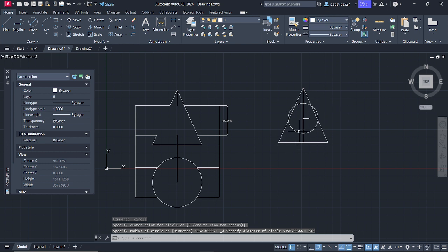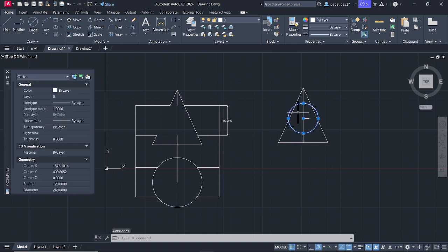Now you notice this. All right, note this, please. For every development curve you are going to draw, once this circle extends outside this triangle of the side view, you need to check this first. Once the circle extends outside this triangle, it means your curve is going to come from the base of this cone to this other part, and from the top here to this other part.